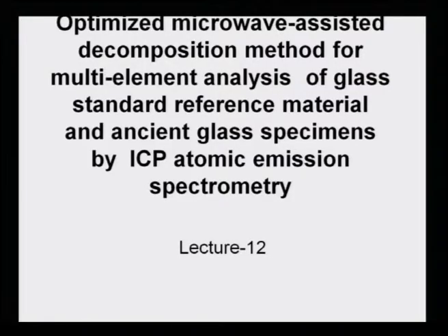Similarly, there are other very specialized procedures for analyzing very special ceramic samples. Here is a method I would describe, an optimized microwave assisted decomposition method for multi-element analysis of glass standard reference material and ancient glass specimens by ICP atomic emission spectrometry.